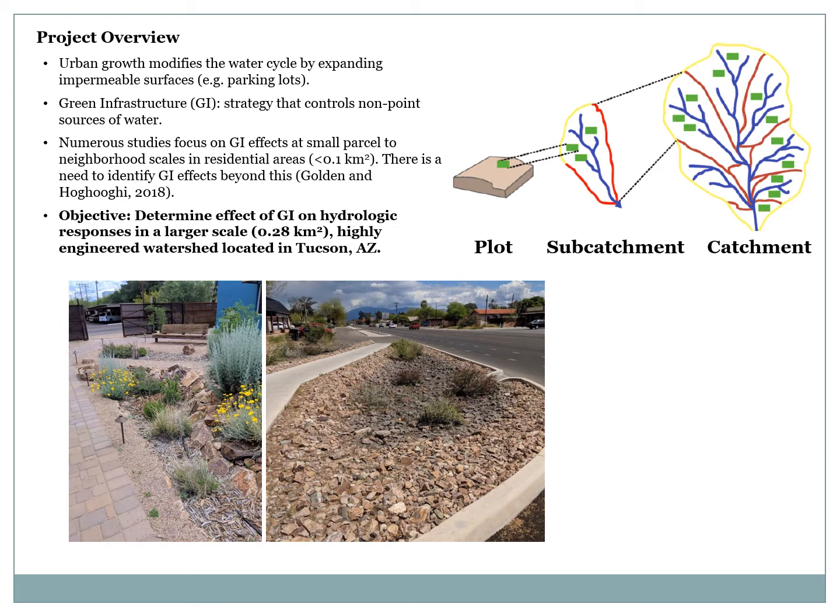So we are seeing an increase in the areas of impermeable parking lots, roadways, sidewalks, and all these surfaces modify the hydrology of the area by not allowing infiltration of water into the subsurface. This in turn increases the risk of severe flash flooding in downstream areas.